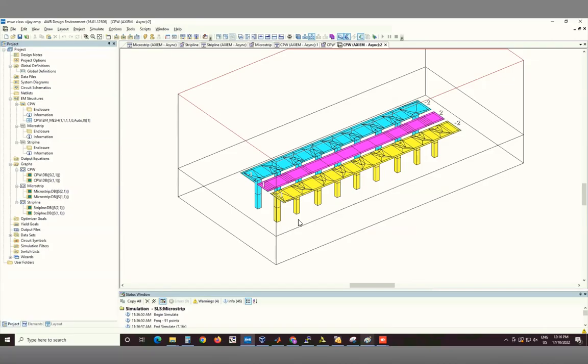There is a more sophisticated way, which is complicated and needs several fabrication steps: you can create what we call air bridges in a lithographic process, versus using a machine called a wire bonding machine. It's literally like a sophisticated sewing machine, where you have a spool of wire, like aluminum. You land it on one metal, and the moment it touches, it applies ultrasonic energy, which melts it, and that wire gets stuck there. Then you move the lever arm to take it up to the next side, do the same thing, and after the bonding, it cuts the wire off. So you can create these air bridges.